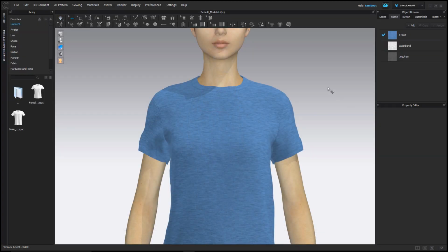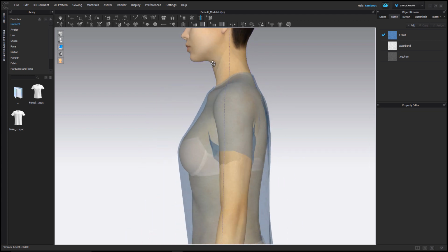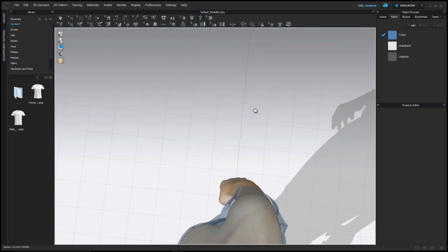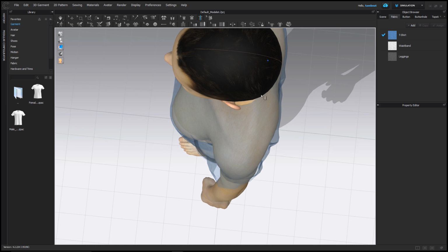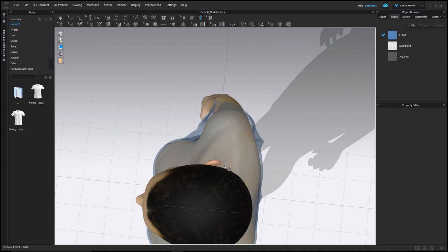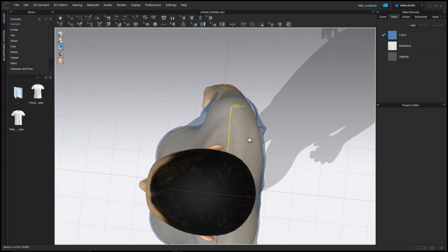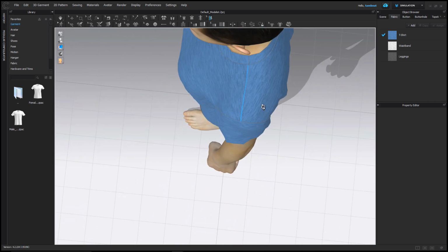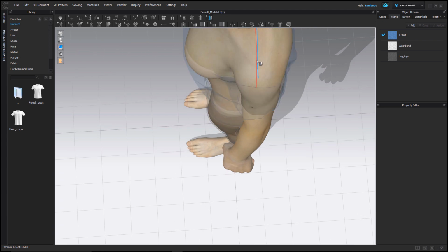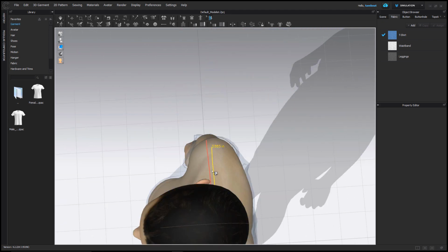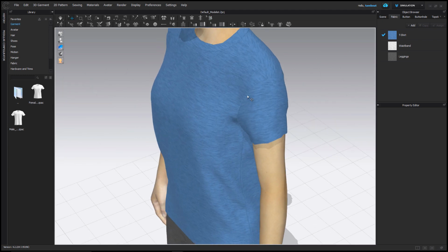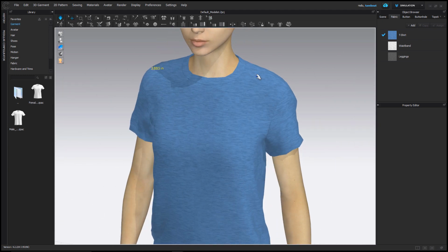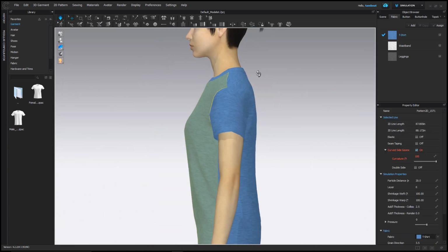Use the linear avatar tape tool to improve fit accuracy by creating shoulder lines to secure to. Oftentimes while working on a garment, it tends to shift around. This way it ensures the garment is laying onto the avatar correctly. Once I finish drawing the lines, I'll use the Attach to Avatar tape tool and select both the shoulder seam of the garment and the avatar tape to attach to. Now when I try to tug on the garment, it retains its fit.